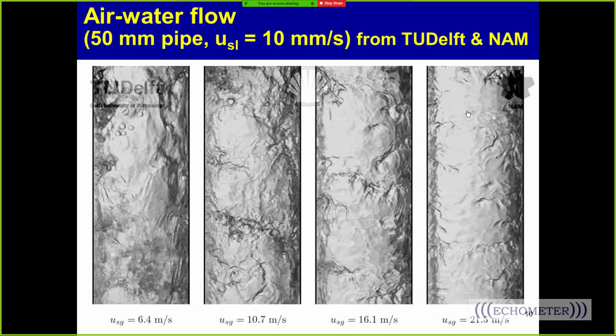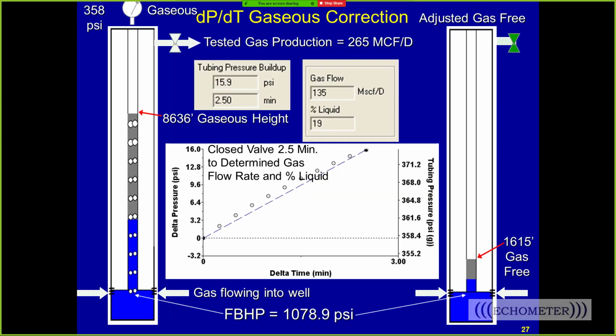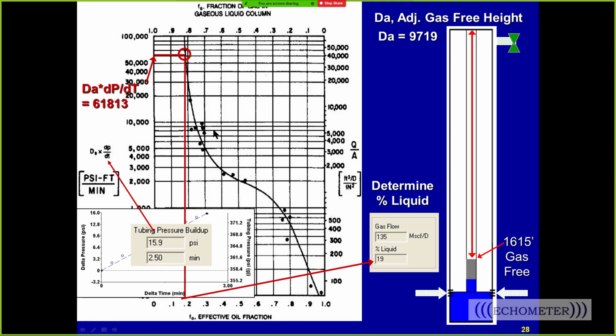And slide number 27, I think: if a well is flowing below the critical rate, how accurate would a single shot be for calculating a producing bottomhole pressure? Pretty good. The correlation that we developed, the S-curve, is good for wells where the gas velocity is below critical. When you look at this curve, it represents the percent liquid in a liquid loaded well. So this is in effect the gradient of the liquid based on the gas velocity.